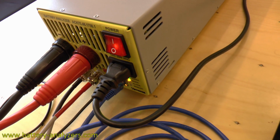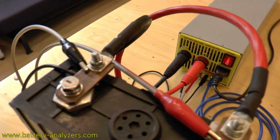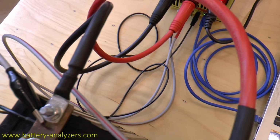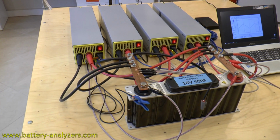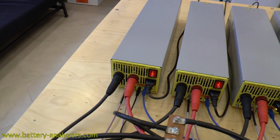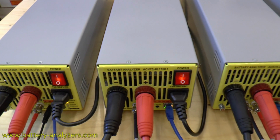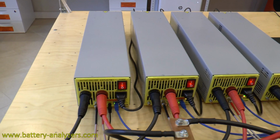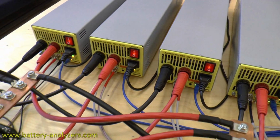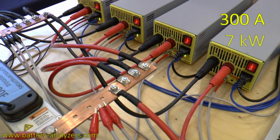The battery is connected to the analyzer for testing in a voltage drop compensated circuit using two current and two potential contactors. In addition, each device is equipped with an external temperature sensor, with which the temperature of the tested battery can be measured. If the charge-discharge current or the power that can be provided by one analyzer is not enough, the devices can be connected in parallel. In this case, the current and power increase in proportion to the number of the devices operating in parallel. For example, four ACK75.48.1750.1 analyzers can provide a charge-discharge current of 300 amps and the maximum charge and discharge power of 7 kilowatts.